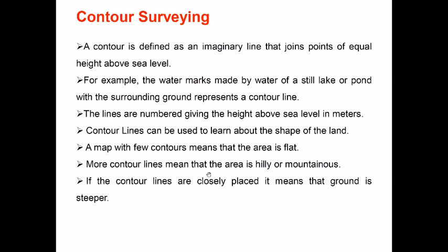More contour lines mean that the area is hilly or mountainous. We've discussed that, because the slope changes very abruptly. And if the contour lines are closely spaced, it means that the ground is steeper.